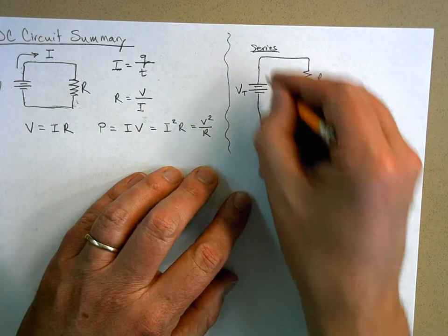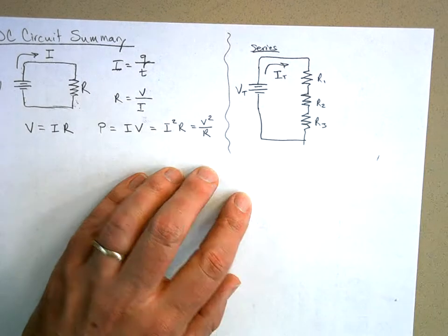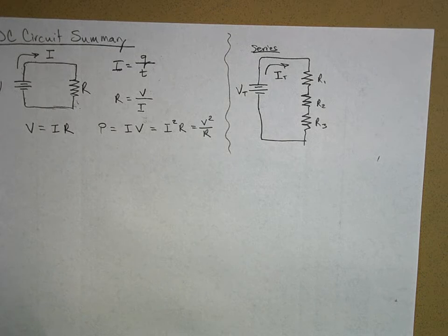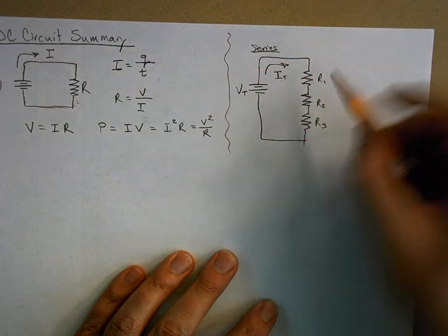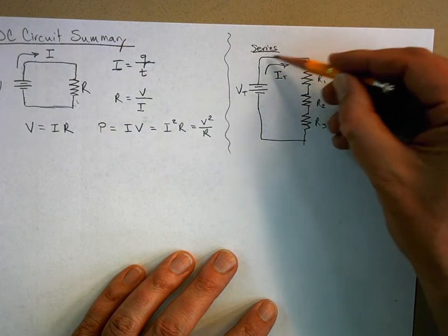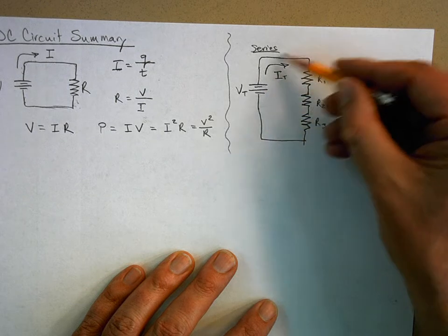Now this is going to push current. We'll call that the total current. It's going to push current through those resistors. Now because they're in series, visualize this. Think about current as being the flow of material stuff, electrons, through this wire. And if I've got 5 coulombs per second moving through here, I've got to have 5 coulombs per second going through everything in that circuit.